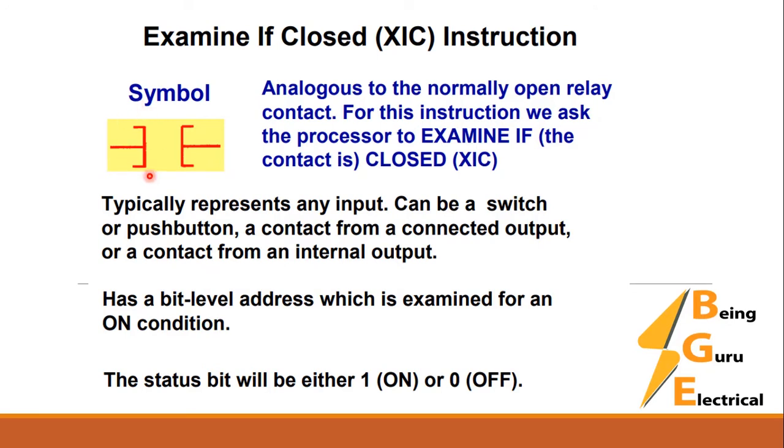Now see, this is called the examine if closed instruction. This is the symbol, analogous to the normally open relay contact. Like for the normally open in PLC programming language, what we call this is examine if closed.